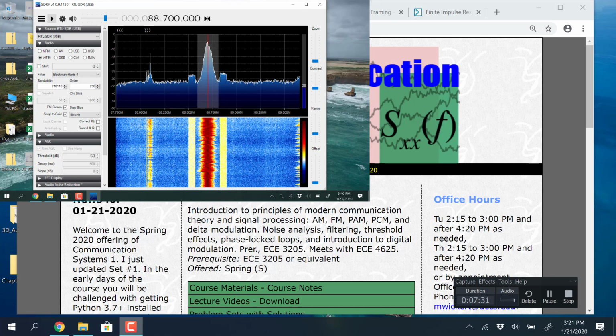So can I think of it like barriers? Basically saying it won't pass these. No, it's not that it's barriers. It's that they said there was so much spectrum. There's about 200 kilohertz of bandwidth allocated to each FM spectrum. And then there's a guard band that the FCC uses. They don't typically put two stations right next to each other.